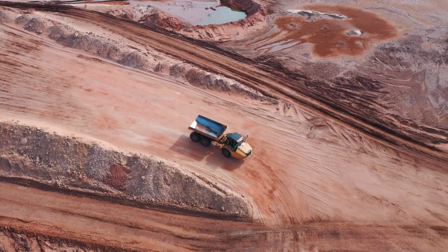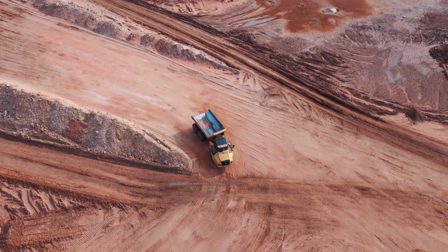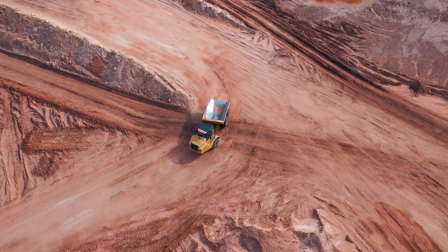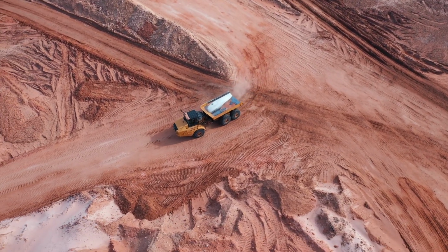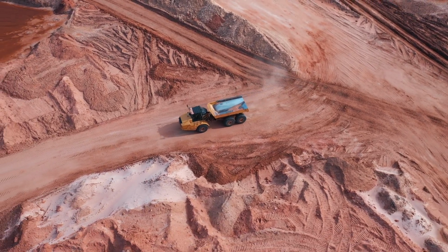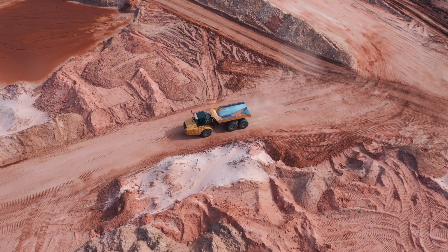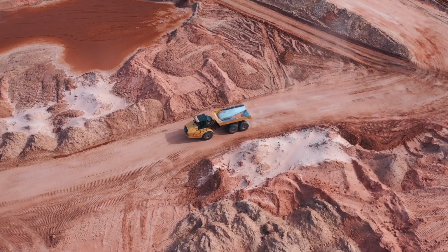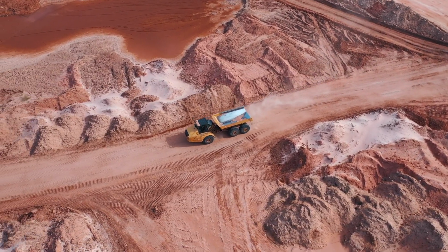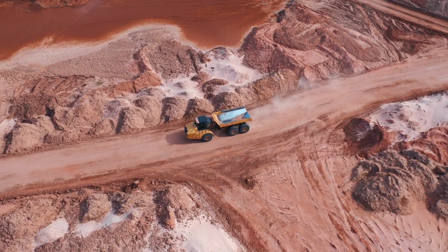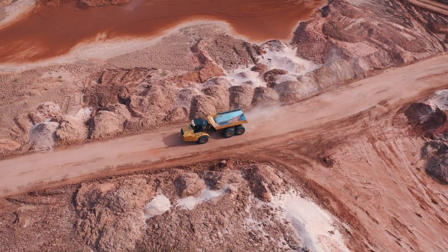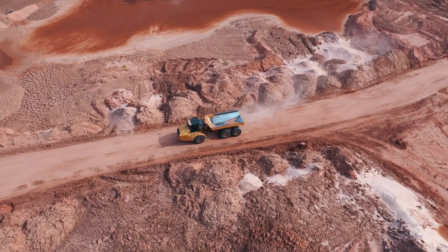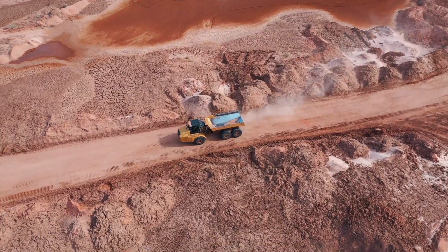Road work. While operating on traveled roads, keep right, especially on corners and hills. When pushing out a road, avoid pushing debris, for example, stumps, trees, rocks, and dirt, into standing timber. Do not create hang-ups. Be aware of any dead limbs of a tree that may endanger a worker and hung-up trees as they are encountered along roadways.